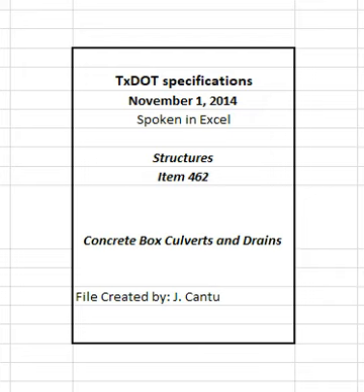Finish stub ends for connections to future work not shown on the plans by installing watertight plugs into the free end of the box. Fill lifting holes with mortar or concrete and cure for precast boxes. Precast concrete or mortar plugs may be used. 3.5 Extending. Break back and extend existing culverts in accordance with Section 420.4.8, Extending Existing Substructures, and Section 422.4.5, Extending Existing Slabs, as applicable.